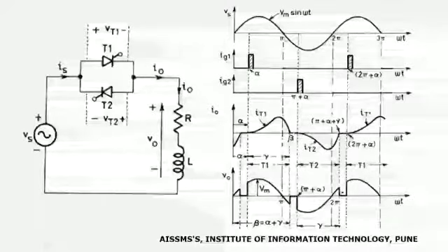At an instant pi, the source current Is will get reduced to 0. The source voltage will also get reduced to 0, and after instant pi, the direction of source current and applied voltage will get reversed. But the load is having an inductor in it, and this inductor opposes this change in the current which is supplied from the source.